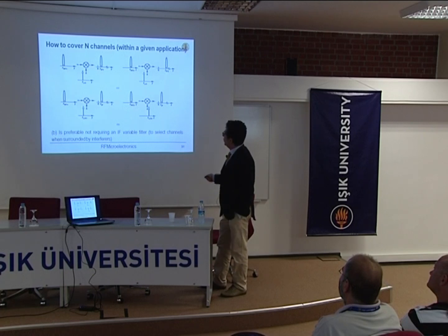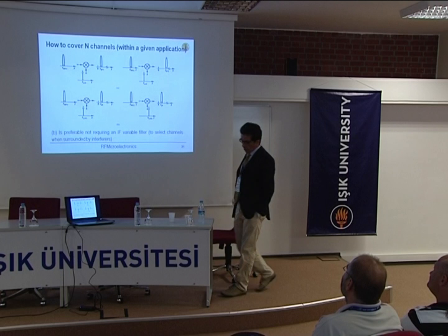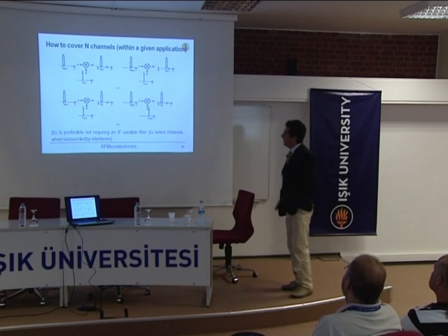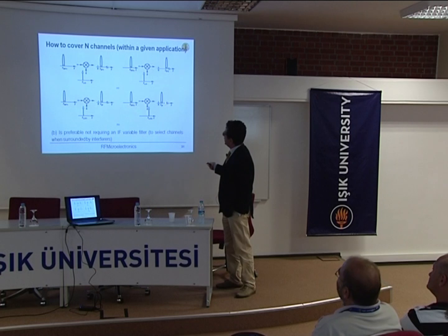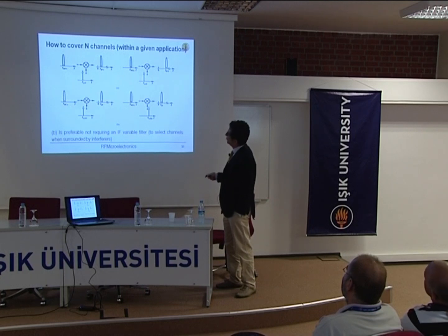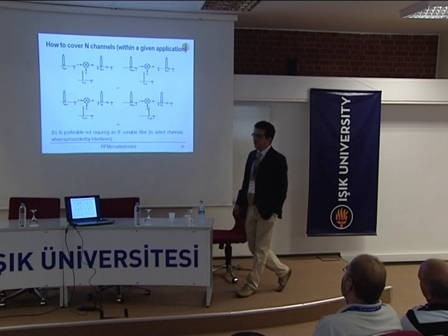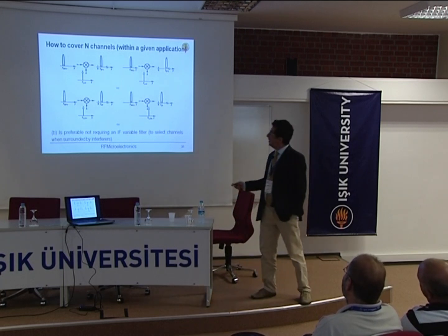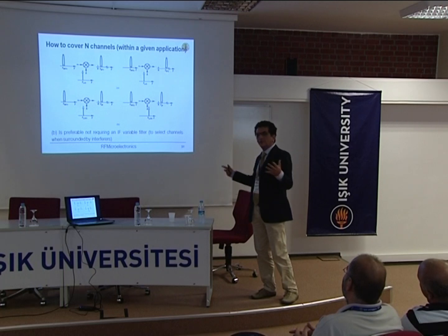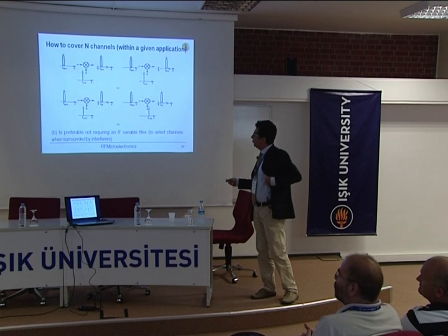Usually, I would say always, designers opt for this second possibility, where you have a tunable on-chip local oscillator, which is easier to do than having an intermediate bandwidth occupying a wide spectrum, which is basically the same spectrum occupied at the antenna. Think about the filter at IF: it would be a filter with a very wide range, which should span the overall band of the application.